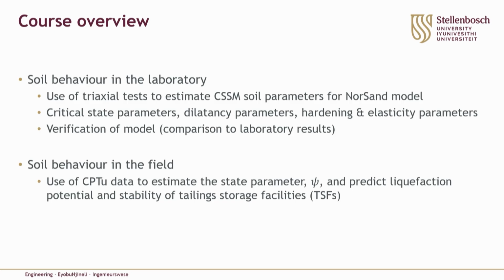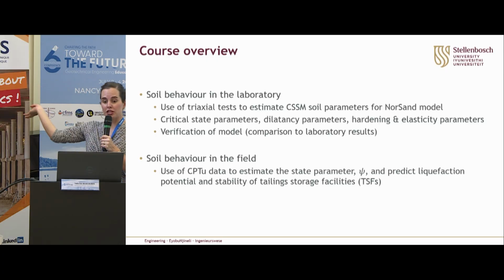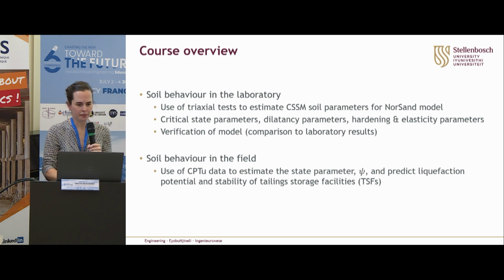So the overview of the course: the aim in the laboratory was to look at how we use triaxial tests to determine the critical state soil parameters and to verify the model that we have. And then the field section looked at the use of cone penetration test data to estimate the in situ state parameter and to predict liquefaction.